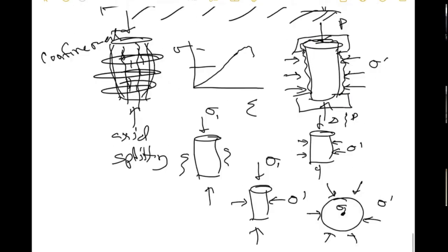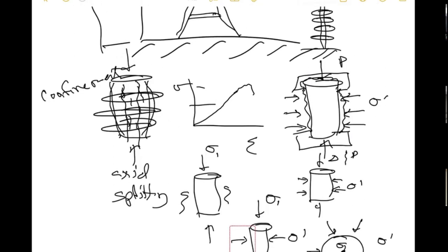And so if we go back to this stress strain curve, if you now apply confinement, what will happen is it will get stiffer for the reasons that Yoon King said, because it's more compressed, those initial cracks or whatever's in there. It'll tend to get stiffer, and it will go up higher till it fails. And then in the brittle case, it'll go all the way down because it just splits apart. There's right away no more load carrying capacity.